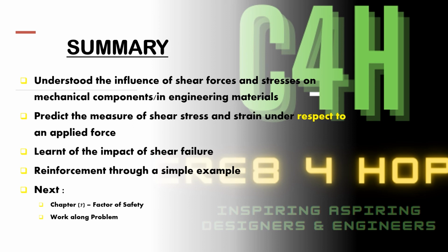We've also had a look at different equations to enable us to measure the level of stress and strain with respect to an applied shear force. We've also talked a little bit about the impact of shear failure and looked at different situations related to fasteners. And we've looked at a very simple example of how we can use the concepts learned today in reviewing geometric parameters for fasteners in particular.